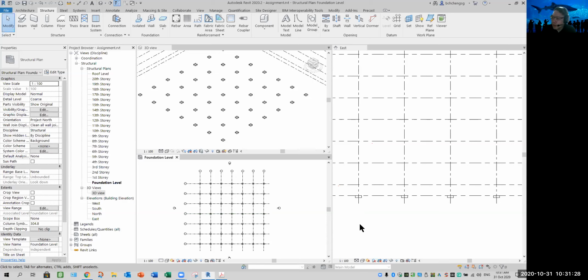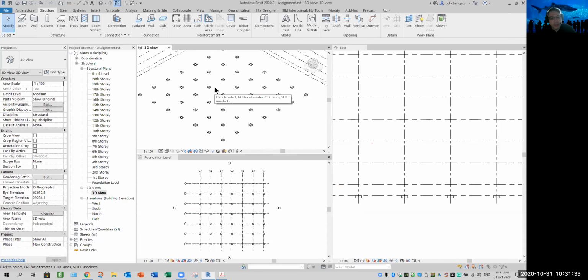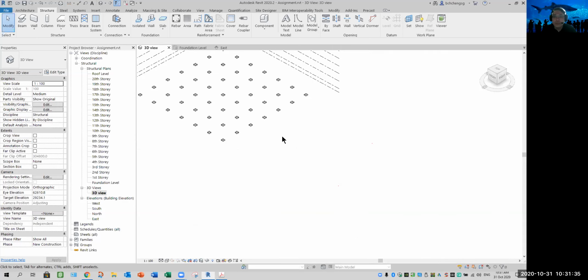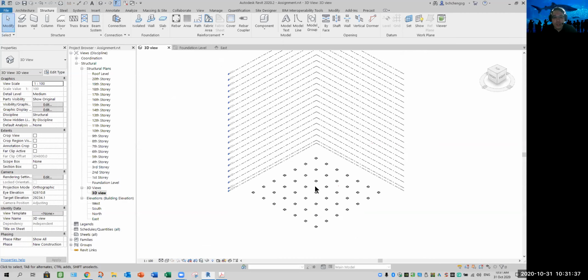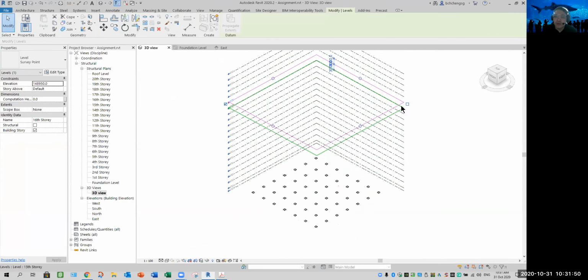Let's look at one view at a time. In your 3D view, let's say I maximize by typing TW. When you are using Revit 2019-2020, you see that your level in your plan, how you extend to get them joined. You can see that you can select from here and adjust. This is how you adjust the grid. And when you go to your elevation, you can see your level line will also expand or extend.